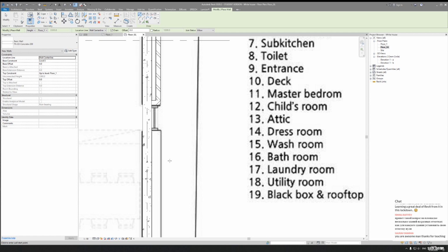Yes, you should create two different levels for each building, and better if you, for example, create one building in one file and another building in another file. So you will get two files with two buildings with different levels, but once you connect them in the coordination file, you will get everything right, though you will get more levels than you have, of course. Anyway, you will get a structurally right file. So separate it and use different levels. It will not mistake you, it will not mistake your colleagues.